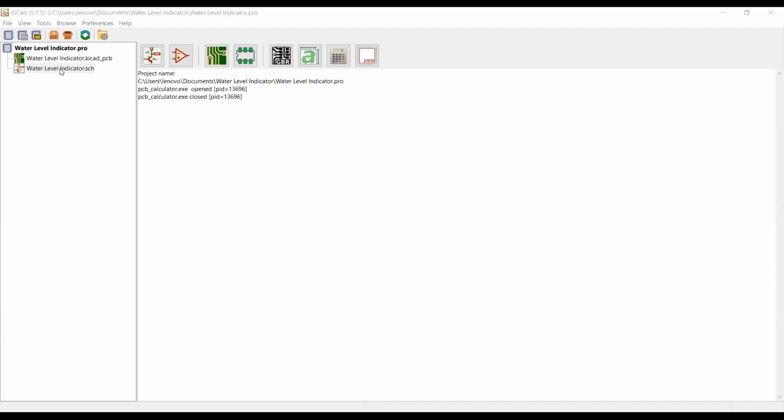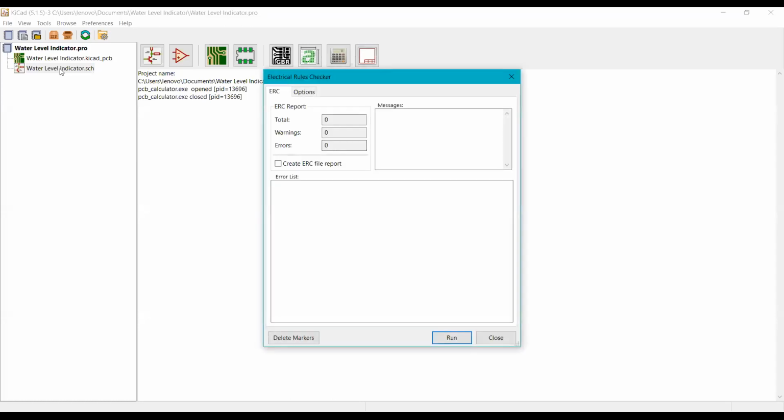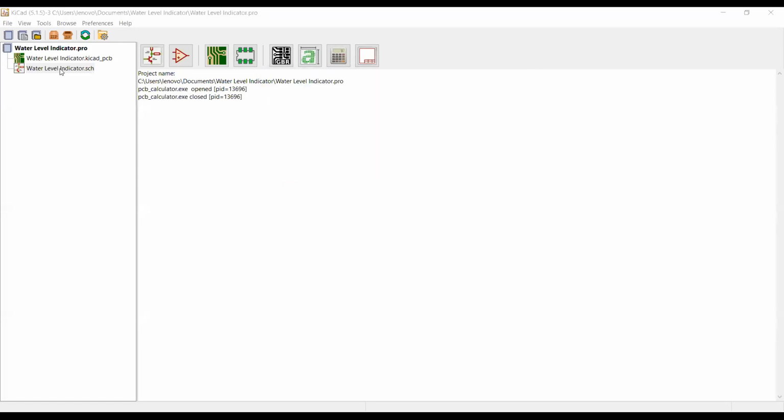Like if there is any mismatch or uncomparable connection or pad between these two files, .sch and .kicad_pcb, it will give you the error, and then you have to remove the error to have the finalized and successful Gerber file. This is the DRC, design rule check or electrical rule check. In KiCAD, it will say electrical rule check sometimes, and it will sometimes say DRC. I think in Altium and Eagle, it will be known as the DRC, design rule check.